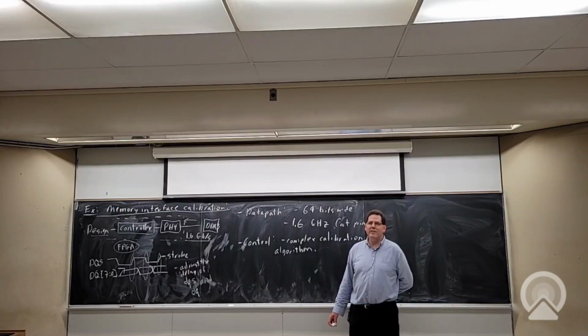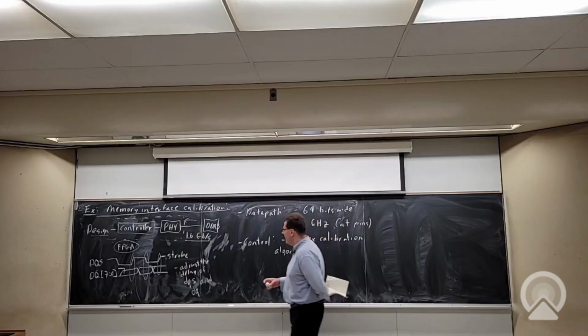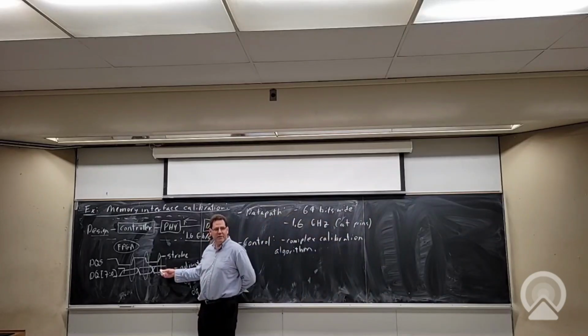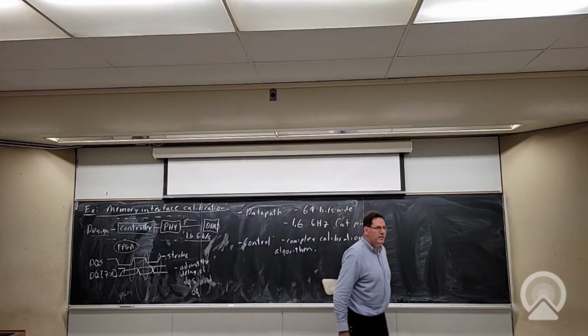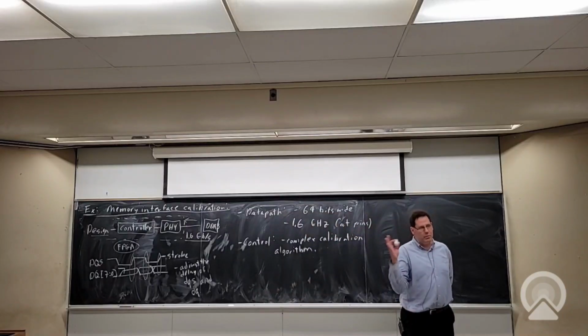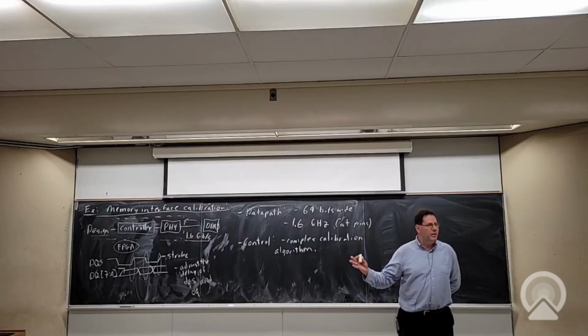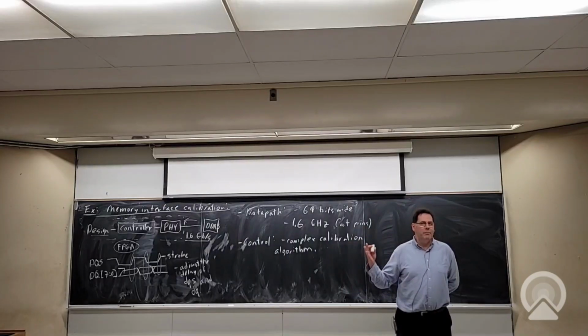So DDR standards are sort of, you have to read them carefully. A lot of companies will brand their DDR by this data rate. Okay, so if you get DDR 3300, it actually means 3.3 gigahertz. The clock is actually half of that. Does that make sense? That's the rate at which the edges are occurring when you count both edges.